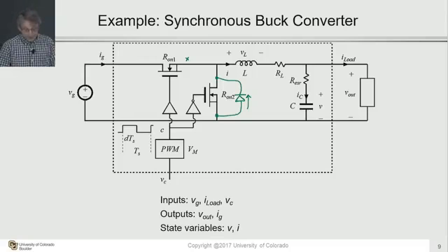But if in the process you actually turn on this MOSFET right here, you will have the current actually flowing through the channel of the MOSFET from source to drain. That's actually opposite of what normally the current would flow through a controllable MOSFET. And that MOSFET really serves the purpose that the rectifying diode would serve in just a regular transistor plus diode buck converter. Now, this MOSFET, let's call it Q2, and Q1 are turned on and off in a complementary manner. You will never have them both on at the same time, of course.